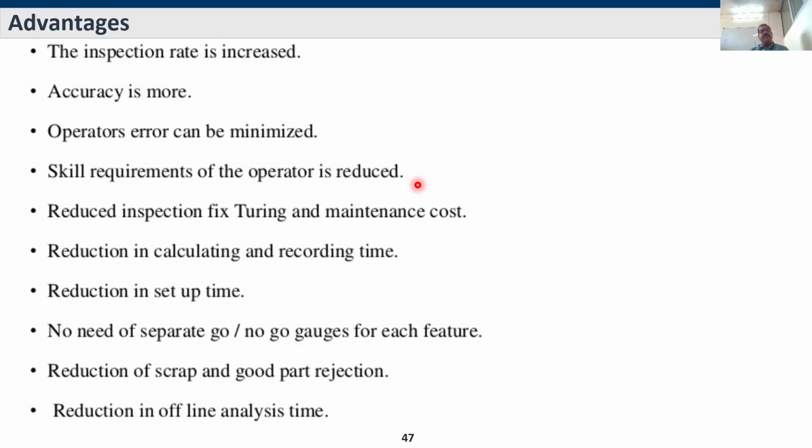Setting up the CMM machine for inspection is much needed. But monotonously, they are mounting the workpiece on the table and turning on the program, meaning automatically the CMM will run the program A, B, C, D like that. A, B, C, D in the sense measuring the whole features, or measuring the width feature or dimensional feature, form features like that. Everything needs to be programmed and given, meaning just an unskilled operator is sufficient for loading and unloading. Then he will only turn the program on and off like that. Then it will be performing.